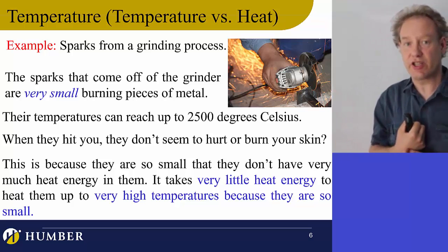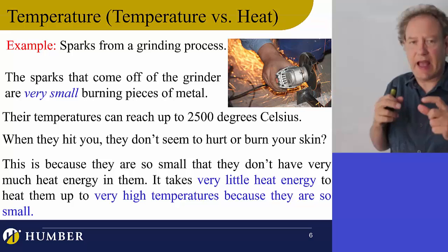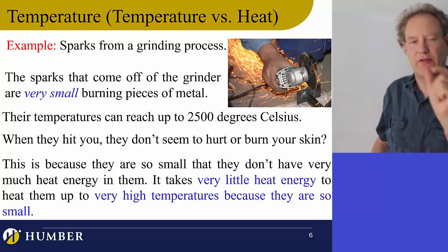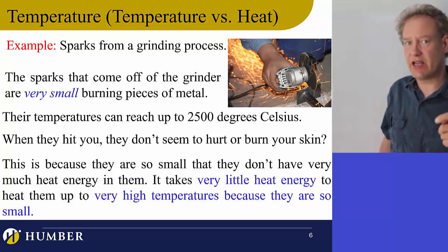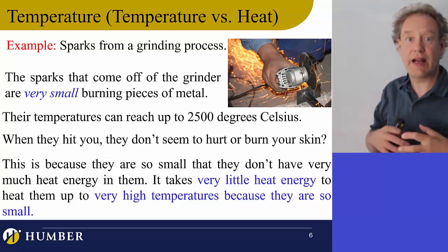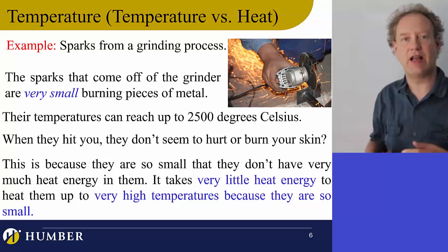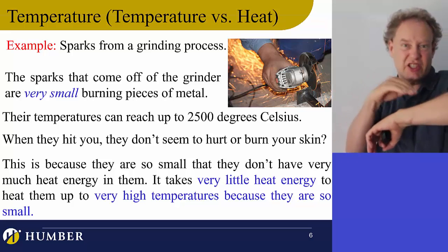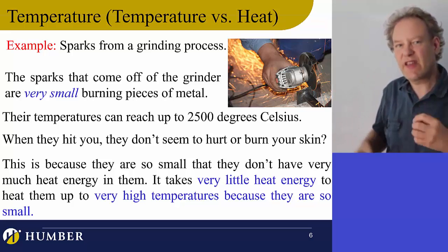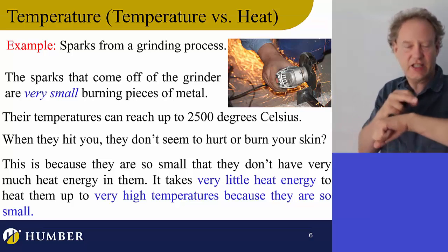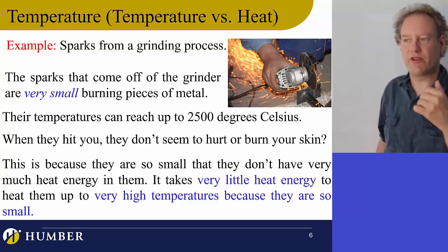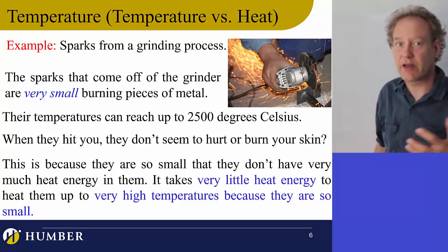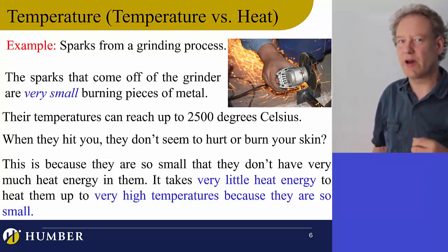Each one of those sparks is so small, and the energy that's in them is packed into this little tiny ball of mass, but it's not a lot of energy that's actually in there. But because it's so small, it ends up that the temperature is really high. So when those bits are flying and hitting your hand, unless they're hitting a spot on your skin that's consistent, it won't actually burn your skin, because the thing that burns your skin is the heat energy doing damage to your skin. So there's not a lot of heat energy in those sparks. Even though their temperature is 2,500 degrees Celsius, it's still not going to burn you. So I think that maybe helps unpack that a little bit more.